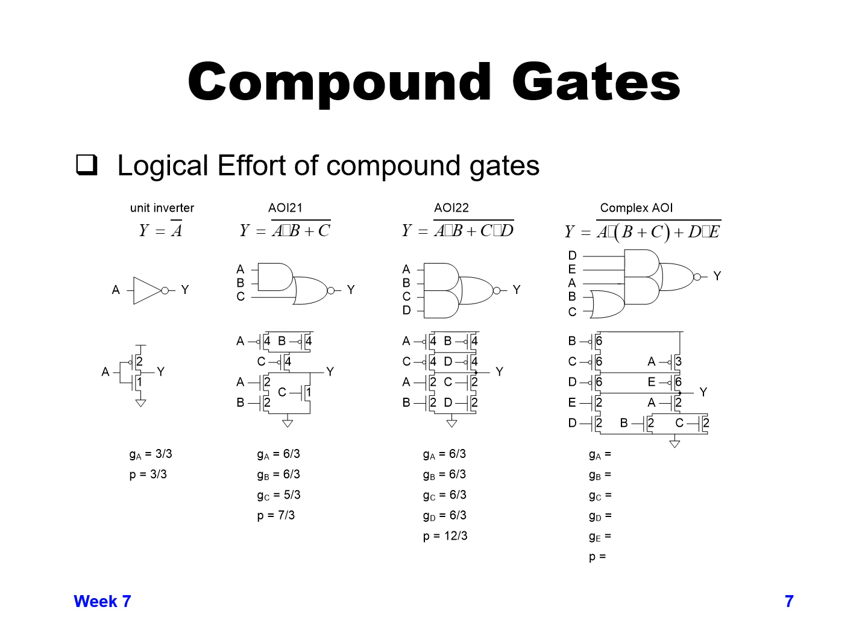Going on to the final, more complex gate, where we have B or C ANDed with A, and then that is NORed with D and E. And so for that complex function, the sizes are down in the bottom. If we go through for A, we have size 3 PMOS, size 2 NMOS, so we have 5/3.